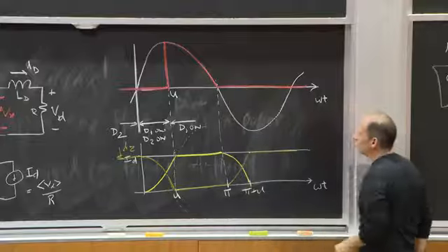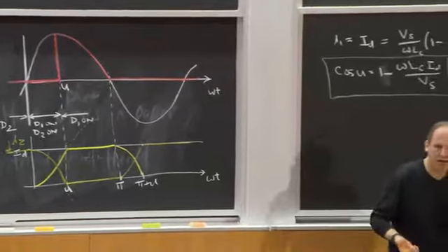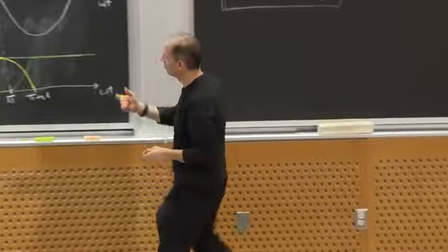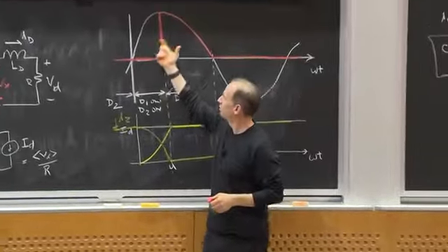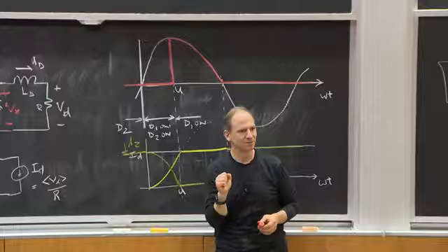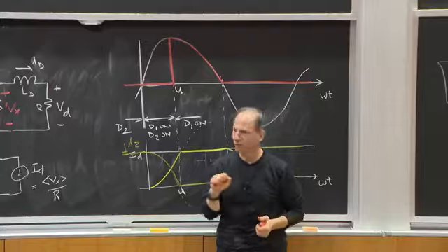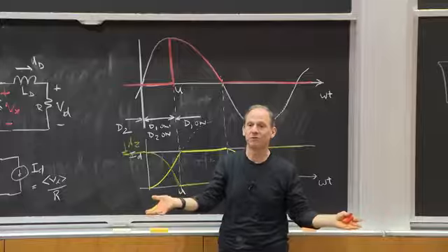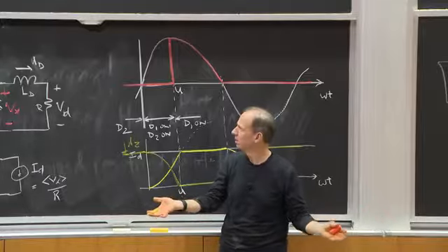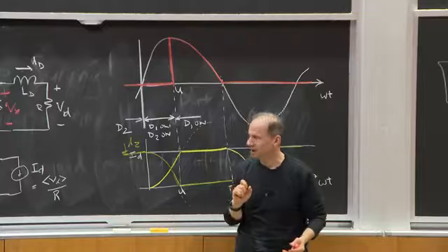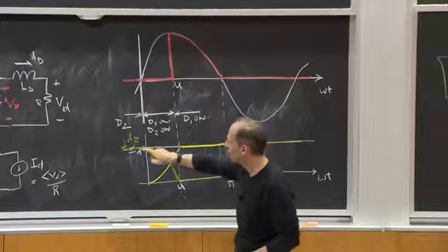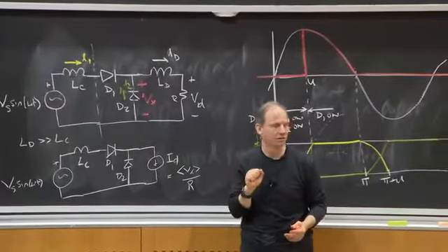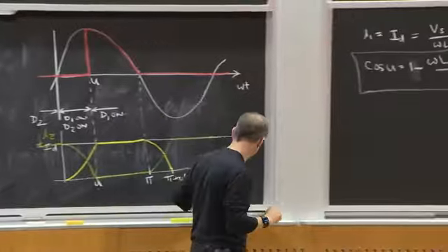Okay? So what happens is, once I have this commutating inductance, or commutating reactance, in there, I take a bite out of my half sine voltage, okay? And remember, this is the thing that we're sort of averaging to get our output voltage, right? So now let me say, what is the average voltage? What's the average of Vx, which is the same thing as the average of Vd, okay? Well, I can calculate that.